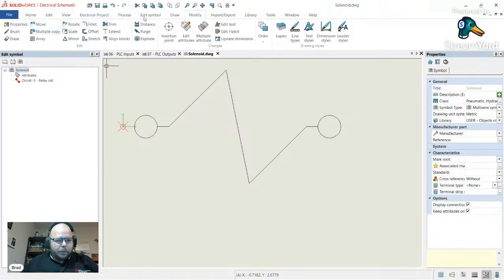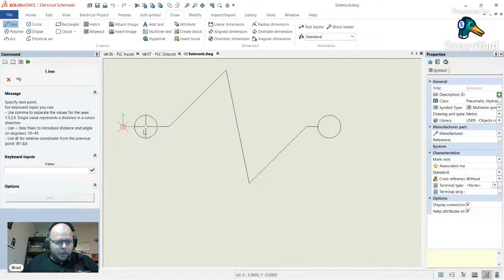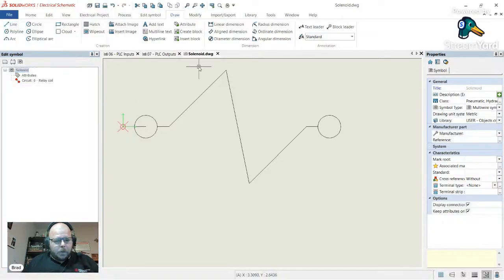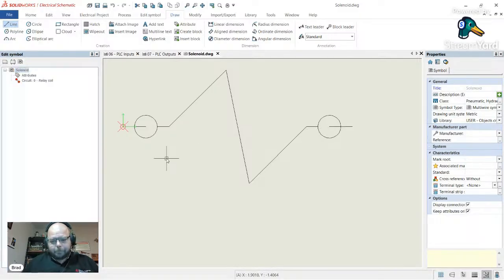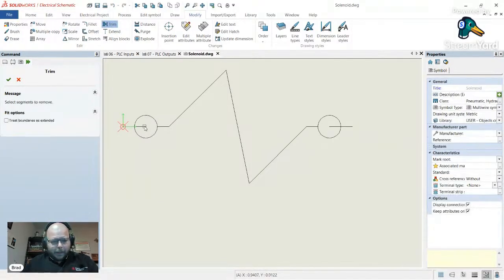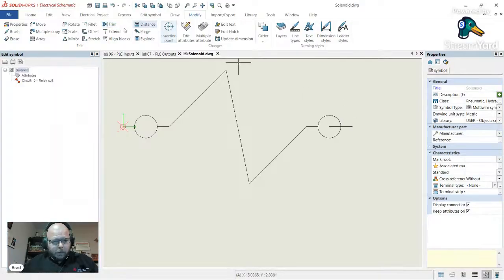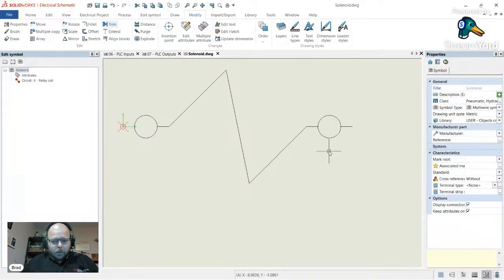And then I need to get those lines that I deleted back in here. Draw a line from here to 0, 0, and then draw a line from here, and I'll retrim to 10, 0, and then trim both of those. Modify trim. Circle is the cutting item. Trim the middle. Okay, and then I got to get out and do it again. Circle is the cutting item. Trim the middle. Okay, good.